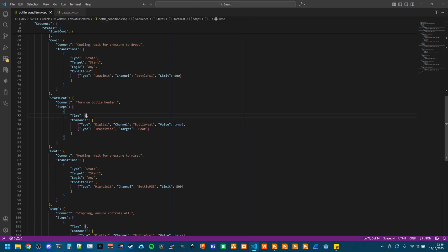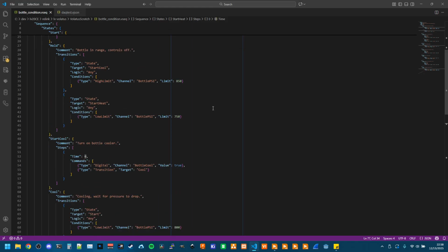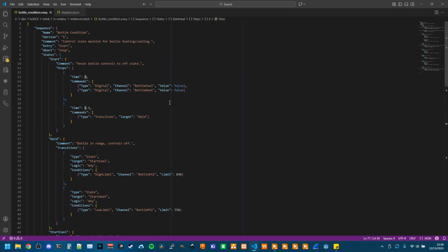So you could specify time down to 2 decimal places with this current implementation and the 10 millisecond period being hard coded into it. But this lets you do more complex automations, and you could load and run multiple sequences in parallel. Right now, there are no checks for any competing control. I'm thinking I'm gonna leave that up to the discipline of operators, and they'll just have to be aware that if they're running a sequence that is going to compete with another sequence, to expect bad behavior.